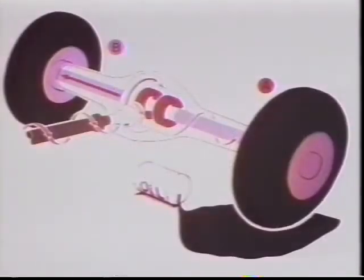This causes the side gears to be forced from the pinion gears, pressuring the clutch plates to engage so that the wheels cannot slip. This lets each wheel turn at different speeds, with the clutch packs transferring some of the power back to both wheels. When a wheel slips, this mechanism prevents the slipping wheel from taking all the power.